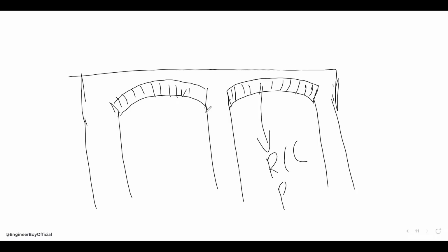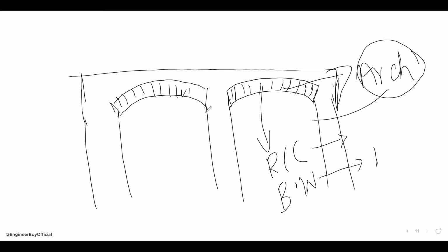These can be brickwork as well. Now, in order to determine other materials from RCC and brickwork, maybe you can say number of bricks, maybe cement, maybe fine aggregates or coarse aggregates. If it's RCC, you have to determine the volume of the same arch. It means knowing about an arch's volume is very important for a quantity surveyor, right?